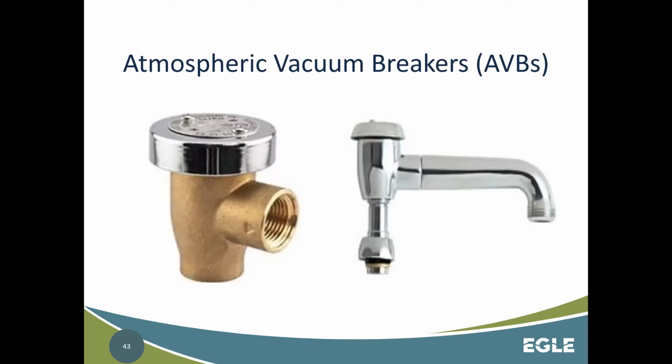Atmospheric vacuum breakers. Okay, so atmospheric vacuum breakers are non-testable. As you can see, this is our first quote unquote device. And the reason this is our device is, look, you don't see any test ports off this thing. These typically are found in two places. They're found in slop sinks or lab sinks, and then hose bibs on the outside of houses is typically where you see these. Not to say they can't be used in commercial dishwashers or sinks. I've seen them in those areas too. They can be, but a lot of times they're not, and there's a reason for that.